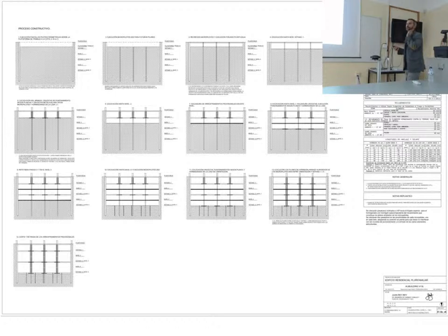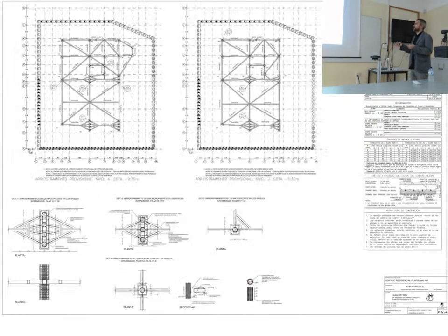So the idea was to first, of course, build the diaphragm wall to retain the soils on the perimeter of the plot. And then we built some micropiles on the positions where we are going to have concrete columns. So we now have micropiles that at the end of the process are going to be concrete columns. These micropiles are going to provide temporary support for the upper levels, and also support the excavation, to be able to support the building while we are excavating. Okay? So this is more or less the process.